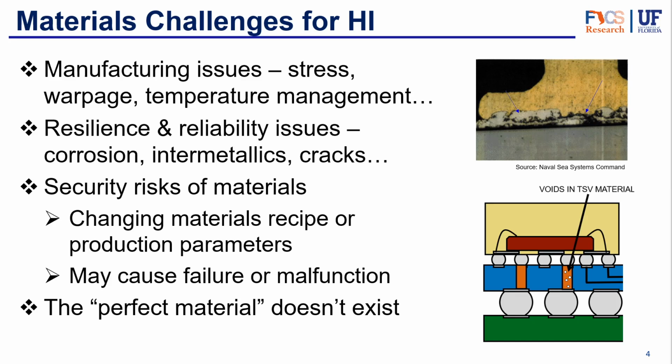However, all of these materials, and especially as we come up with new materials, bring new challenges. And so, what are some of these challenges? Well, one of the bigger ones is obviously during manufacturing. The difference in the CTE during the high temperatures can create stress in the chip and the materials, and this can lead to warpage or other issues. And so, temperature management and warpage are very key components to try to solve during the fabrication process.